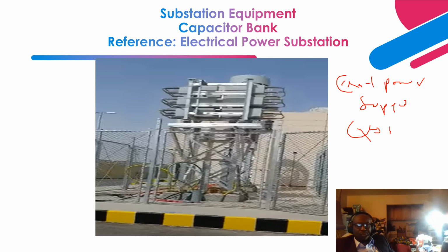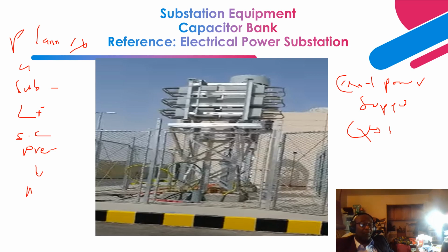During the initial design of a substation, as part of the planning phase, they perform load flow, short circuit studies, protective relay coordination studies, and arc flash studies.